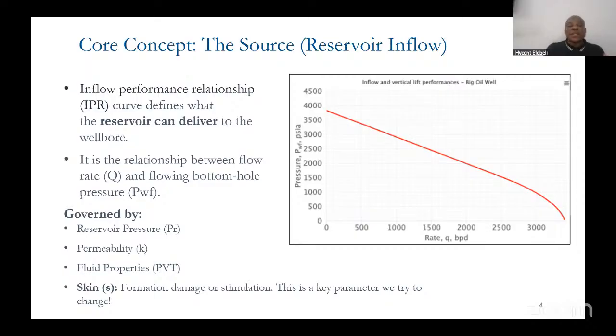You're also looking at solution gas. So those are the things that you are looking at in fluid properties. Then another thing you are looking at is skin. This skin, mind you, is not just about formation damage. It's also about how you drill the well, like partial penetration, for instance. Then limited entry, maybe you didn't perforate enough interval.